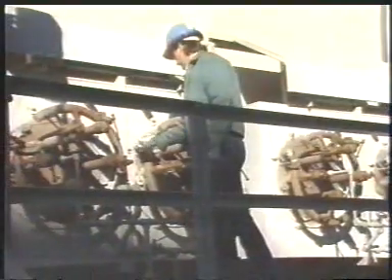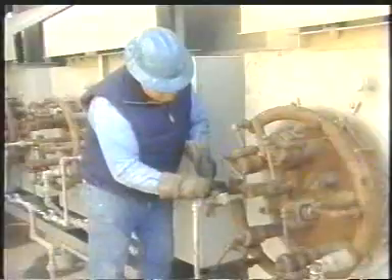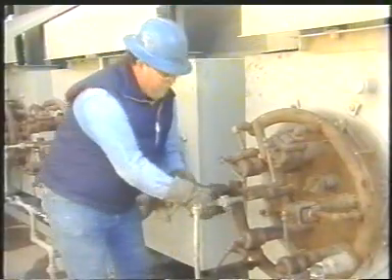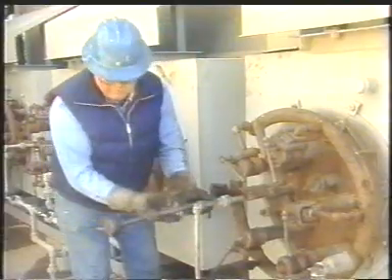Flame impingement occurs when the flames are actually touching the metal surfaces inside the furnace, usually the tubes. This contact weakens the metal and can quickly plug up a tube with coke deposits. Flame impingement can sometimes be corrected by adjusting the position of a burner or by pinching back the fuel supply to the problem burner. If these adjustments don't correct the situation, it may be necessary to remove the burner for cleaning or repair.